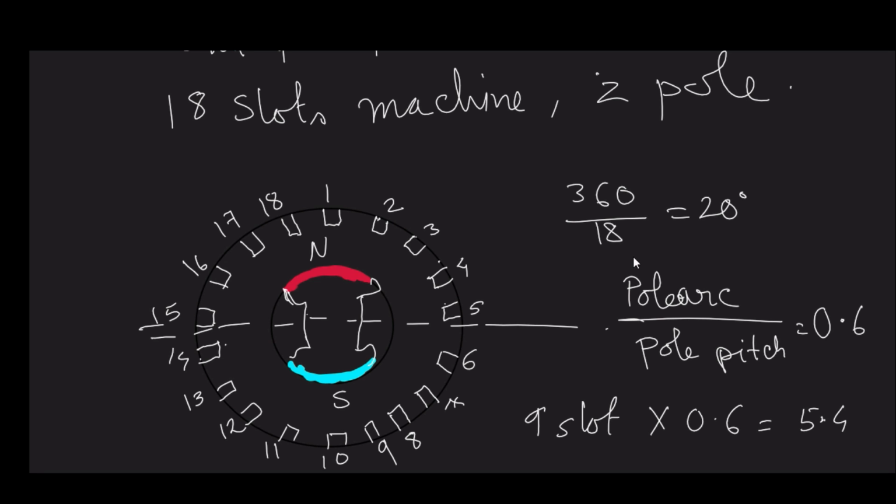In case of salient pole machine, you can understand how difficult it is. In one instant the pole is spanning 5 slots, in the next instant it is covering 6 slots. The reluctance of the entire circuit will pulsate, and thereby it will produce a high frequency harmonic in the induced voltage. That high frequency harmonic may interact with your nearby telephone lines. Do remember that voltage harmonics have a tendency to interact with nearby communication lines. They are very disturbing. It's very easy to understand, not rocket science. So how to solve this problem?